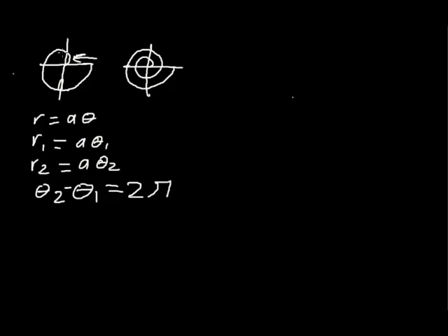If you want to graph something other than a spiral cam, or use only a partial spiral section in your cam profile, you can substitute angles other than 2 pi in this equation. But here we're going to be designing cams where the spiral covers the full revolution.